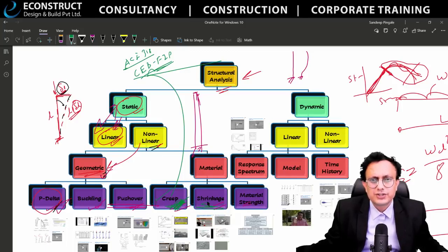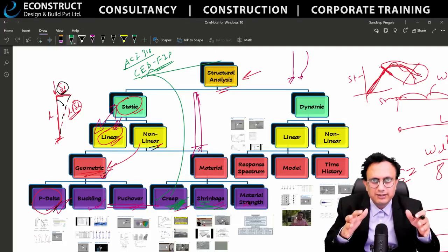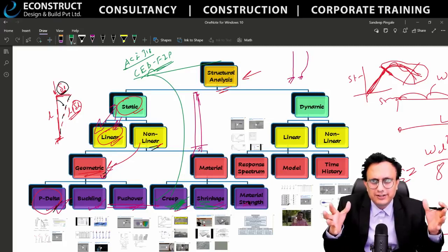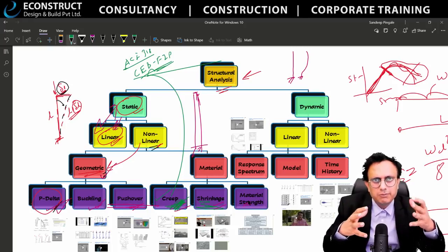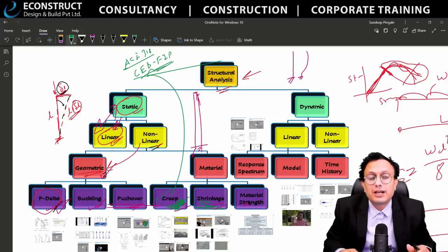What about the shrinkage? Is it needed? Whenever you're pouring the concrete, it is in a semi-solid or semi-liquid kind of form, right? Heat of hydration will come, it will consolidate and all. Then it will start binding, and there will be an initial setting time. If it is not creating the conducive conditions, it will create a crack, which is called the shrinkage crack. Immediate concentrated cracking in the concrete is due to the shrinkage.